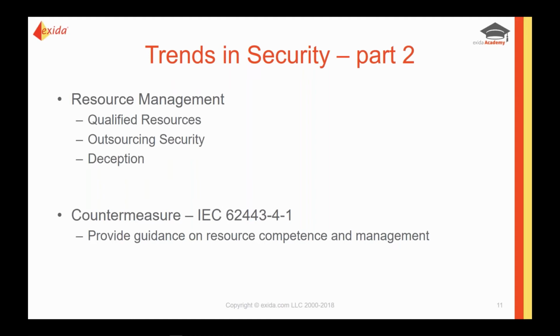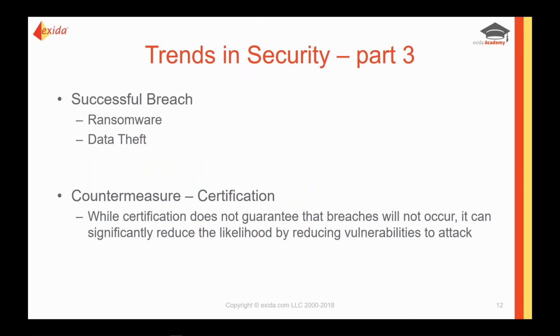One thing comes to mind, perhaps if you're dealing with particularly sensitive areas, you'll want to make sure that the personnel, obviously, that are involved in those areas are well vetted, or perhaps you can use techniques like dual authentication. That actually would be one of the things that appears under the foundational requirements. But there are things that you can do in order to manage and help reduce the likelihood of internal attacks, processes that you can build within your system. And again, that guidance is available in 62443.